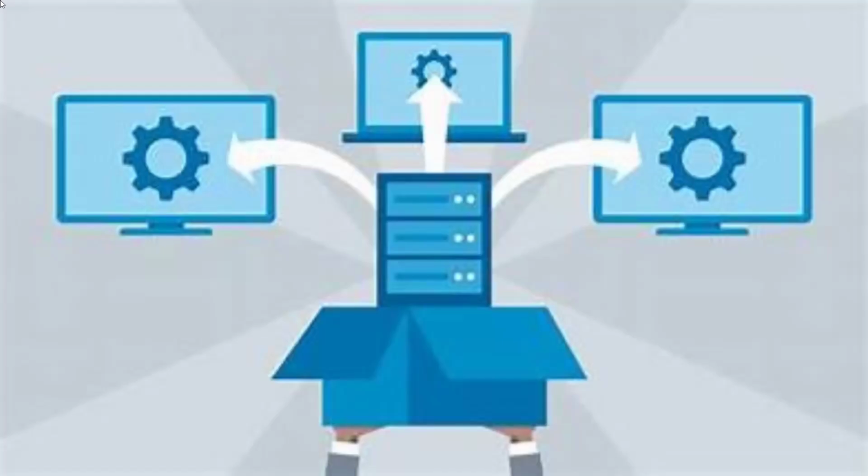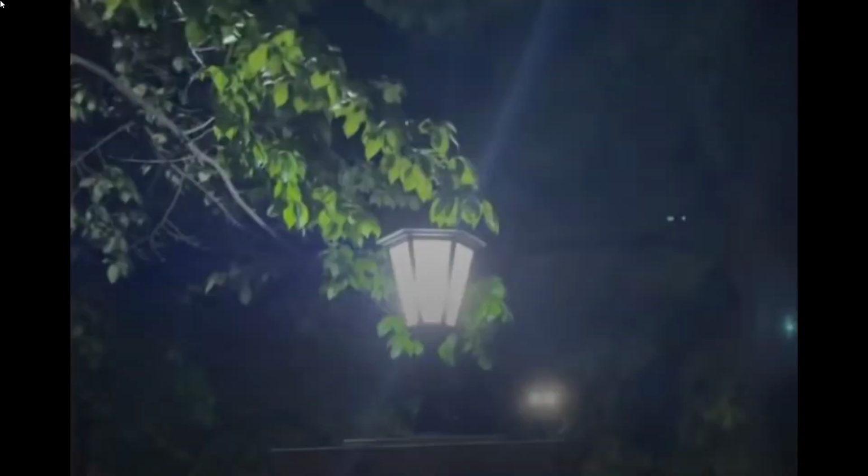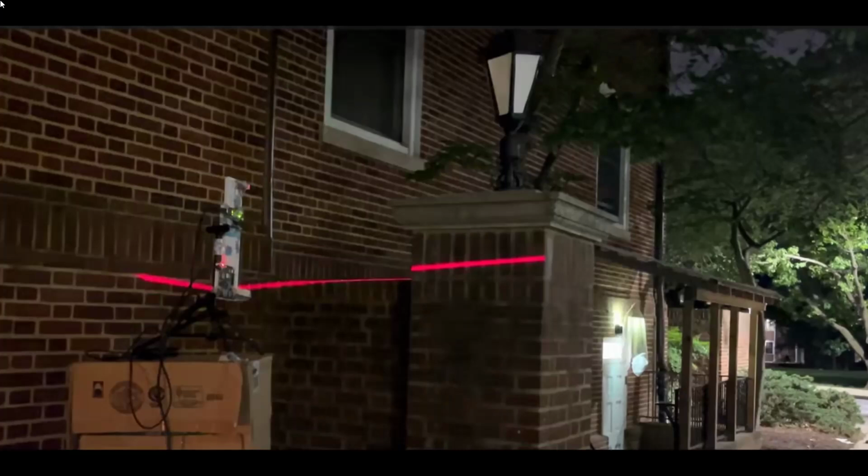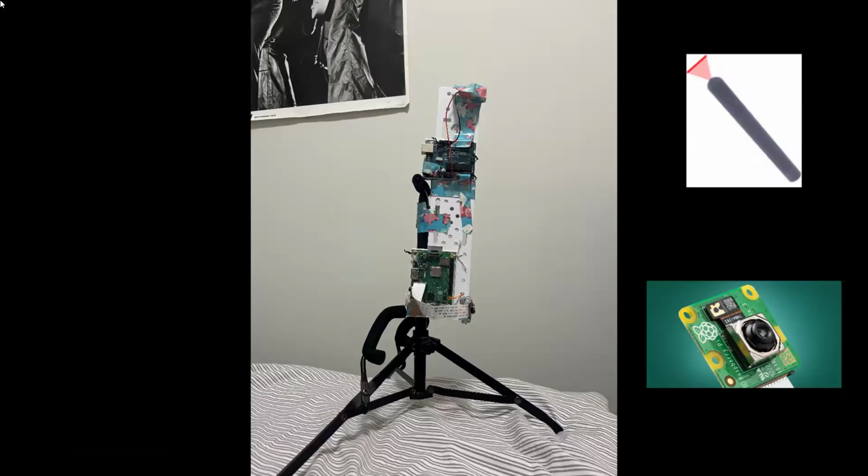The next stage was deployment, which was frustrating. From an environmental standpoint, I faced several challenges. The area was surrounded by bright lights that washed out the laser line, so I covered the reachable light sources with towels and bags. The target itself was about 8 feet off the ground, which I solved by stacking my LiDAR rig on a table, then an ottoman, and then a wide box, and then taping the entire tower together.